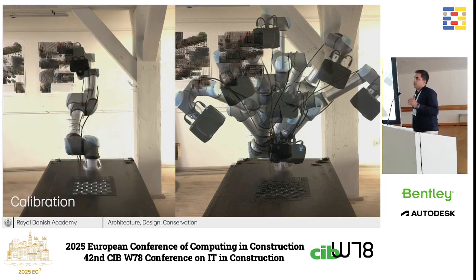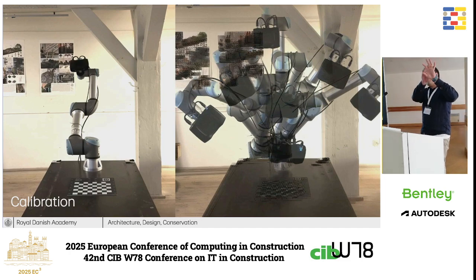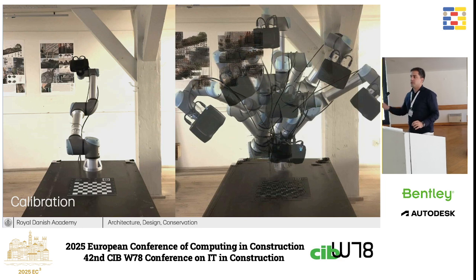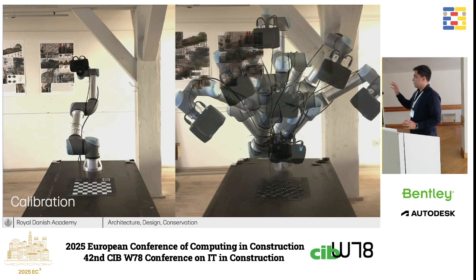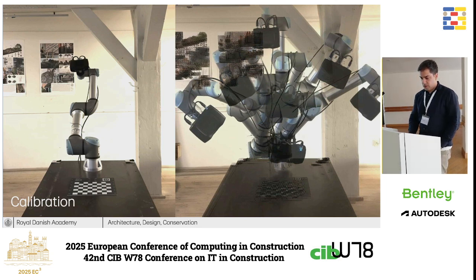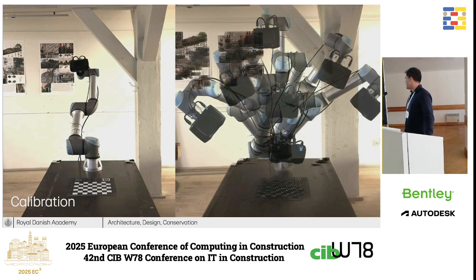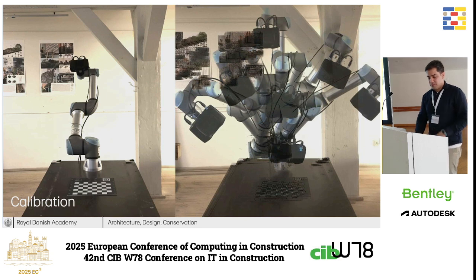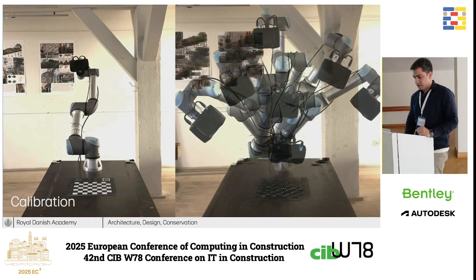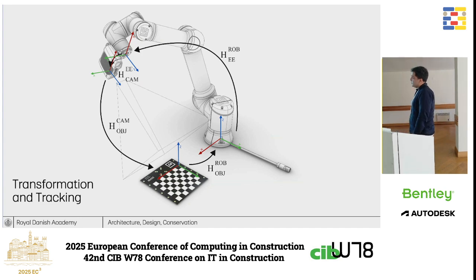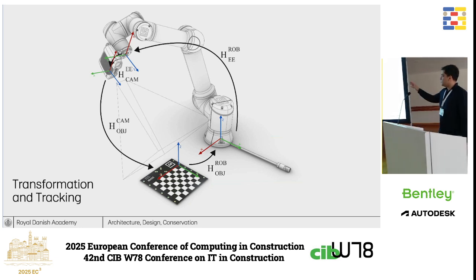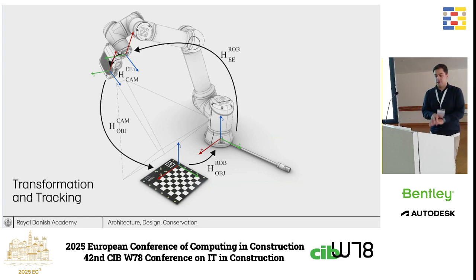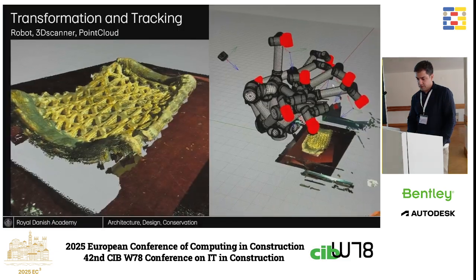Calibration here means finding the TCP of the camera in relation to the TCP of the robot, because usually robots give you the TCP in their library or SDKs, but we need the transformation matrix of the camera relative to the TCP of the robot. I also have to mention that this is one of the hardest parts that everyone struggles with a bit, because it pretty much depends on the user to do the calibration accurately. But when we get the transformation matrix from the TCP of the robot to the camera, then we have two matrices which can auto-align the 3D scan in this plugin.